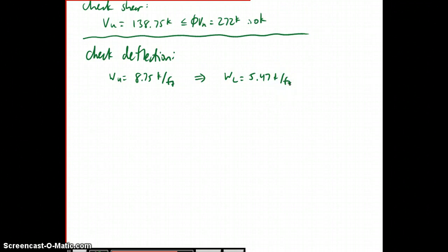So these are two assumptions that we're going to make. They're both conservative. Spreading out a load evenly when loads had previously been higher towards the side will make our deflection greater than our real beam would experience. And then again, assuming the whole thing is live load, because live load is the only thing that comes into play when we account for deflection, is also a conservative assumption. So oftentimes a problem will give you more information. Here we'll just make these two assumptions. And so we know deflection is 5wL to the 4th over 384EI.